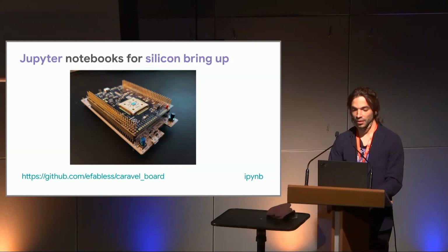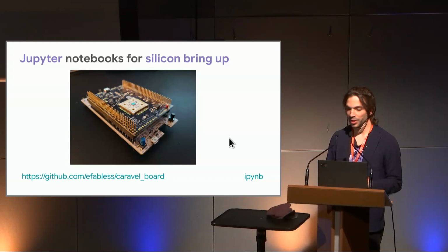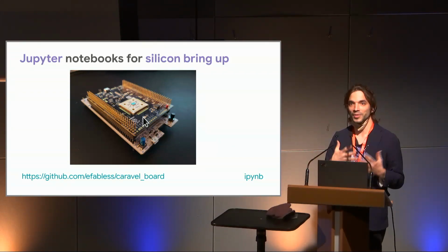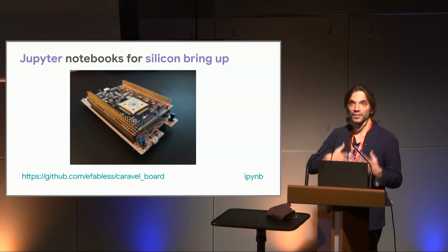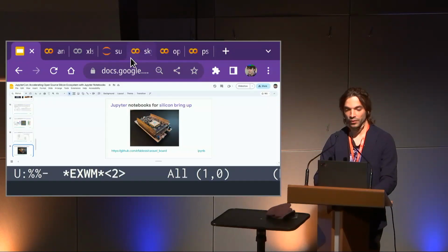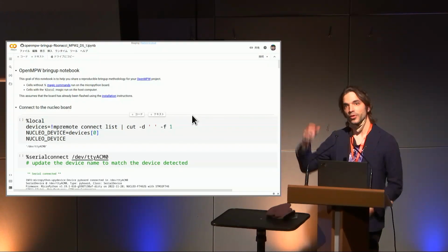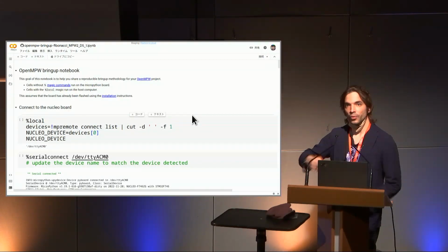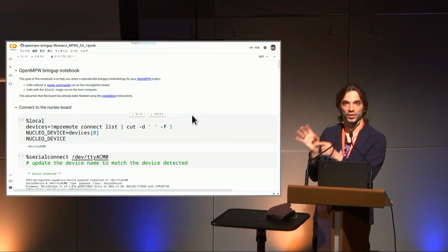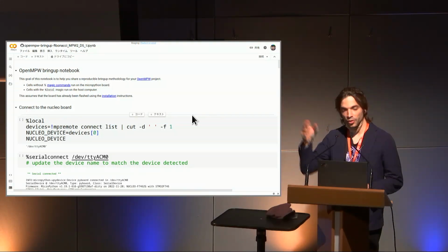And lastly, I also wanted to show how notebooks could be used for silicon bring-up. That's what we ship back to the user, but they have to test now that their design actually behaves like they originally designed and that the silicon is actually working. It's fairly involved usually to bring up some silicon because it requires running a series of commands on your host to accumulate the data, running a series of commands on the test device, and maybe running some command on an intermediate device that will trigger and signal the device that you want to test.